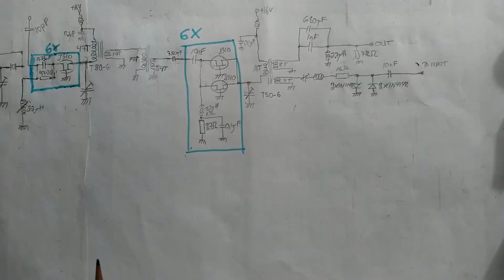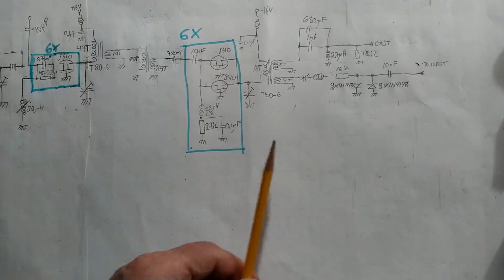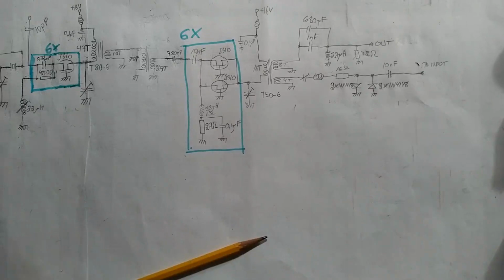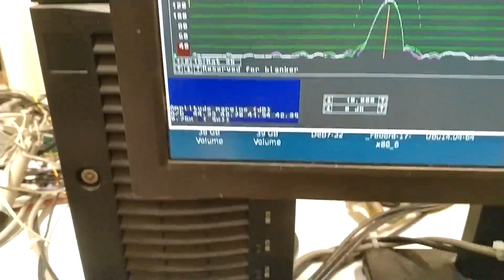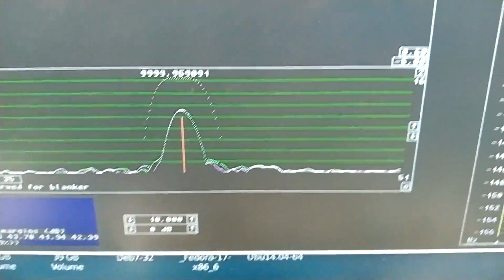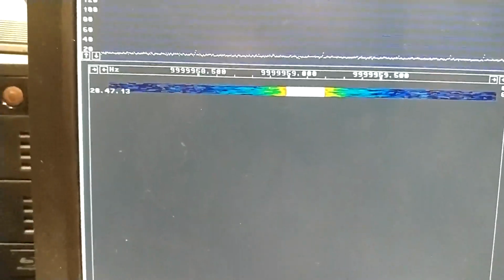I'm still running in the interferometer, injecting a signal here, but this time I'm looking at the limited output here. The signal there is significantly weaker. The limited signal is about 10 decibels weaker, so I have changed the color scale from +5 to -5 to have a similar picture. And it looks similar, and I see no particular noise bursts or so.